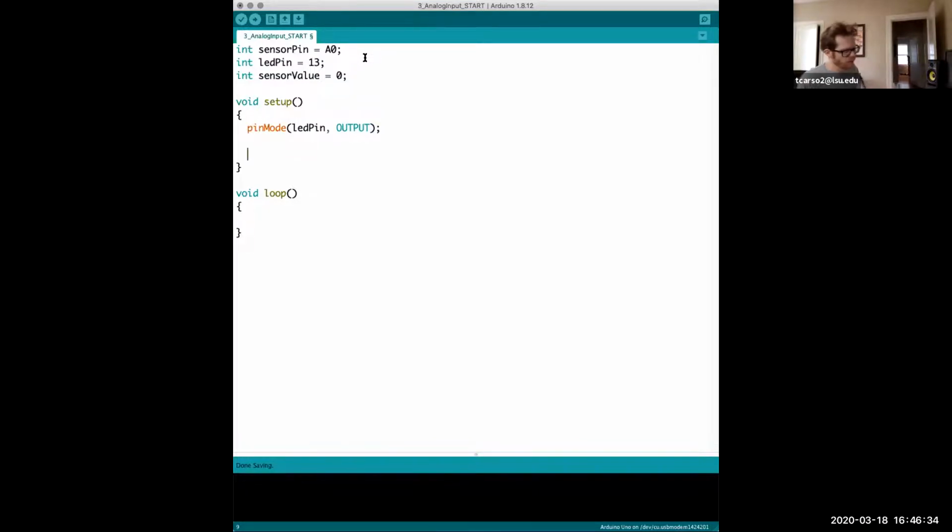And basically, when you plug in something with a USB, it's a type of connection called a serial connection, and so you can monitor the analog to digital conversion and see what value between 0 and 1023 this input is giving you. But to do that, you need to actually start serial monitor. So we'll say Serial.begin, and then we'll give it a speed. I'll explain this later. That's a good speed. It's a baud rate. It's basically the speed of information transfer between this and your computer.